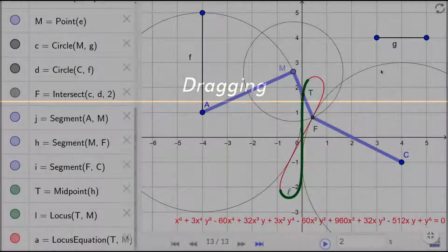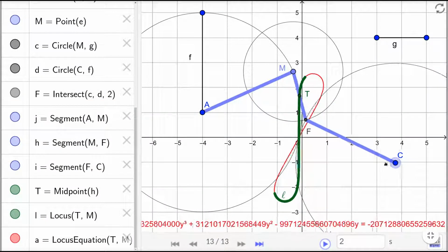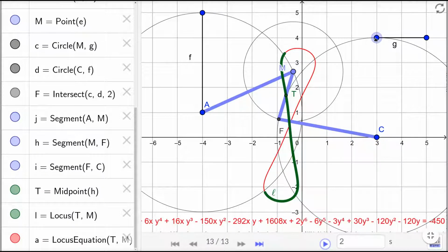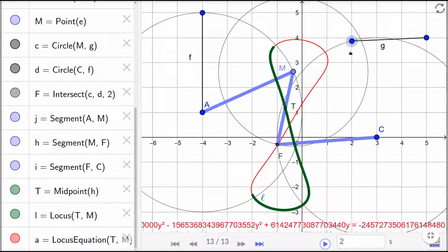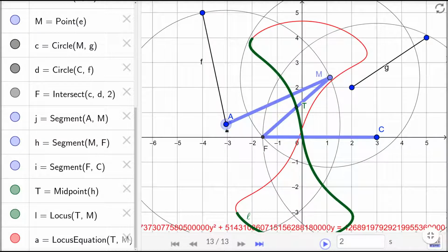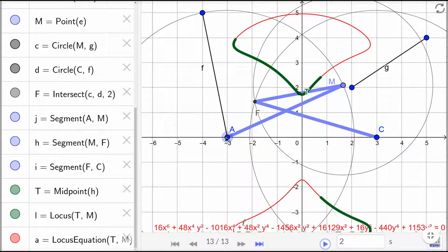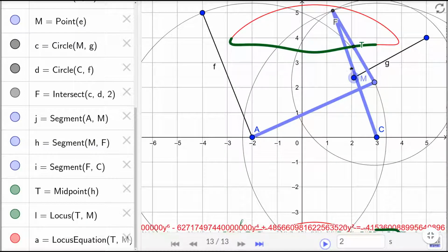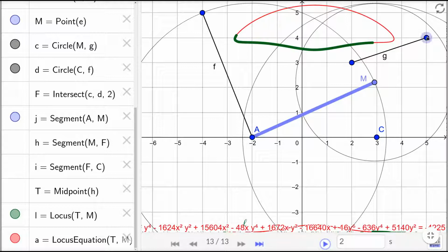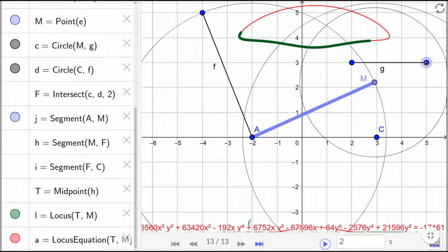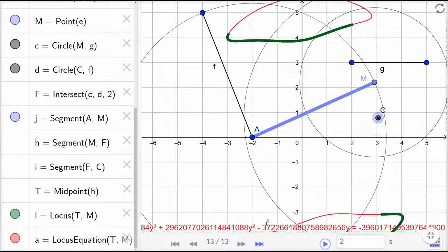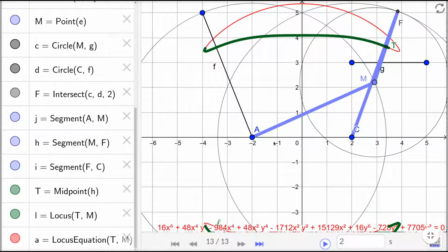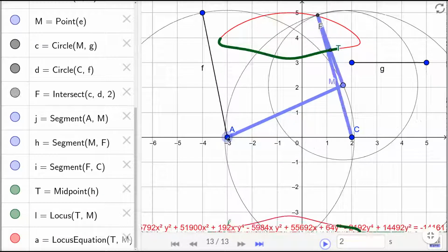Let us consider Watt's linkage again. It is displayed by GeoGebra immediately after computing its implicit algebraic equation, which is a very quick process. In this way, dragging the input points implies immediate change of the displayed curve. After a few experiments, it will turn out that only by modifying the input points, no linear factors will appear. In this way, by doing GeoGebra experiments, we conclude that a 4-bar linkage cannot produce a straight line.